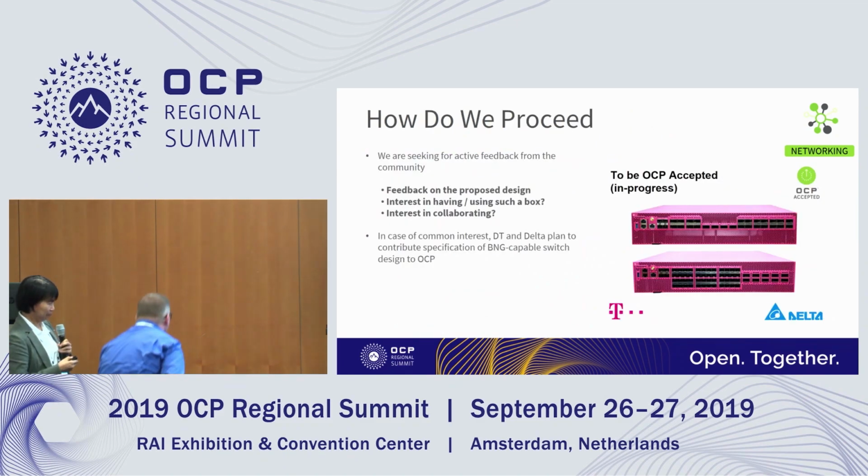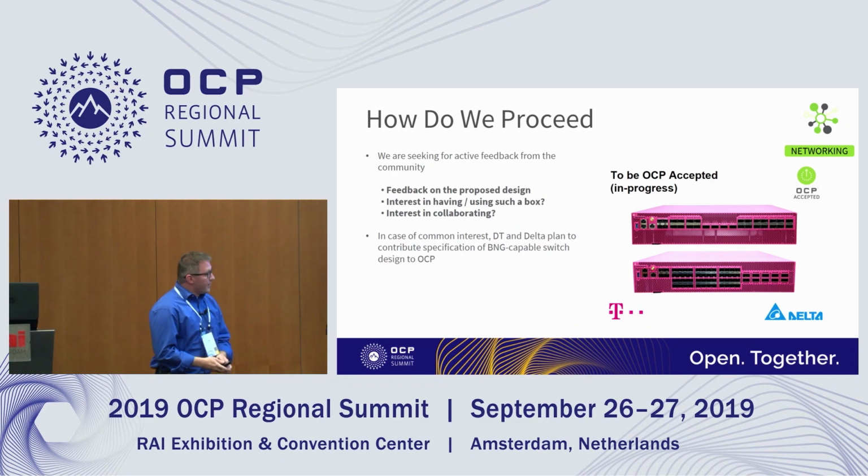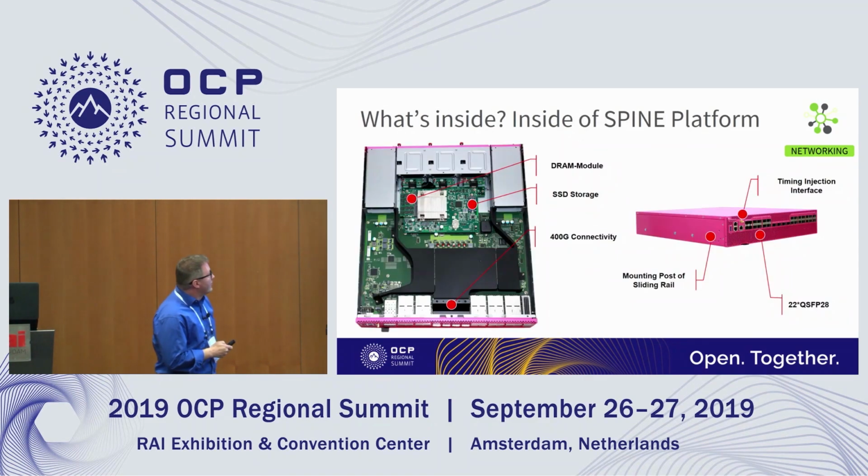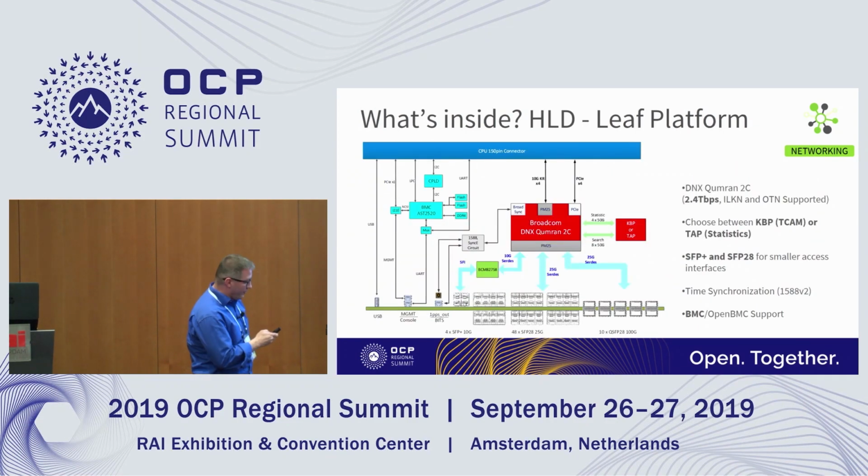Okay, thanks, Winnie. I want to go back a couple of slides and add one additional point in the design which I forgot to mention. Except for the PCIe connectivity between the Broadcom ASIC and the CPU, which Winnie mentioned, we've also introduced 10G interfaces from the PM25 interface of the Broadcom, so SerDes links to the CPU. There are 4 connections provided here, but only 2 are used by the CPU.